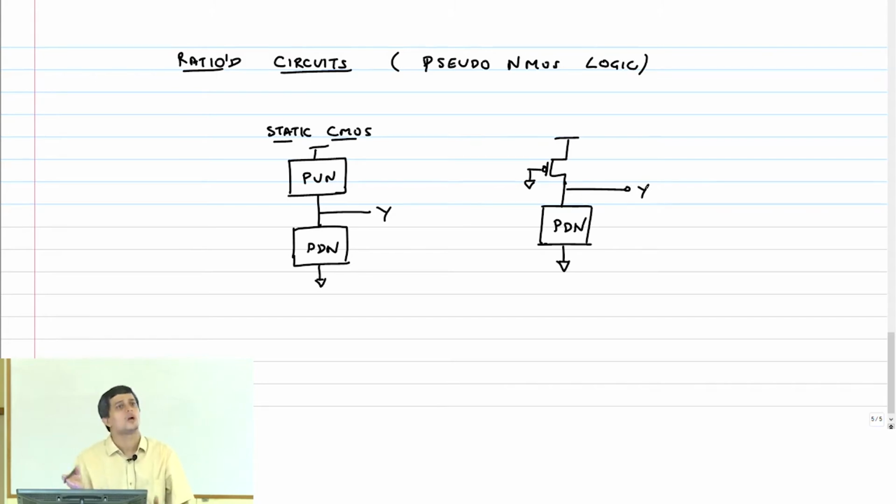But first let us see what advantage we get in terms of the logical effort. What we have been able to do is completely eliminate that PMOS pull-up network, and that is what is your killer for the logical effort always. The other obvious problem is that when my pull down network is conducting and my output is low, will the output go all the way to 0?